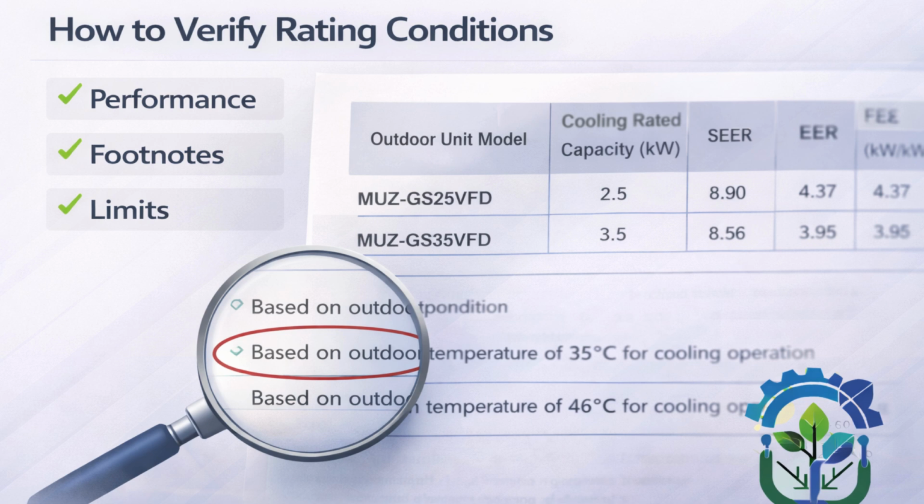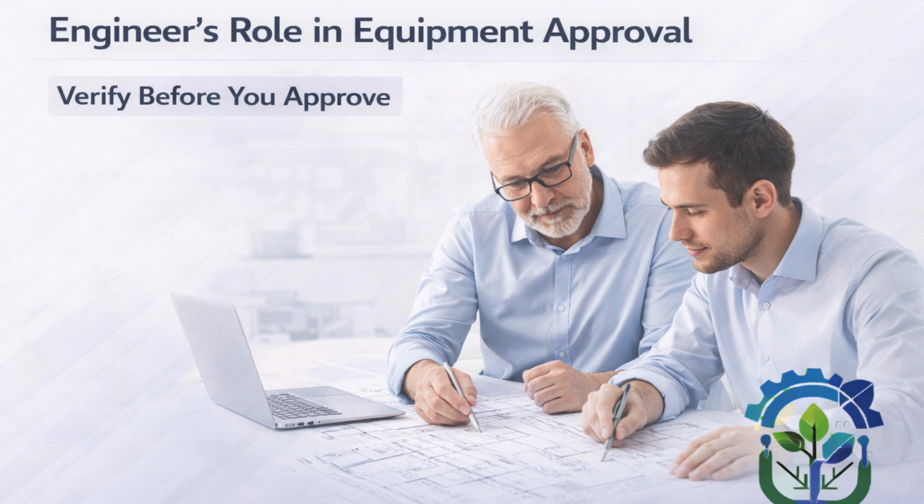If cooling capacity is quoted at 35 degrees Celsius, assume the unit will underperform in the Middle East unless proven otherwise. Approval is not about trust, it is about verification. Basically, senior engineers should question assumptions, read footnotes carefully, and approve based on data, not brochures or verbal communications.